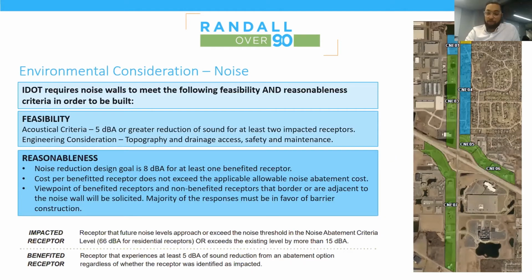Now, I'll briefly summarize what steps are yet to come from a noise perspective. In addition to existing measurements, a traffic noise model will be generated for both no build and build project scenarios with expected traffic counts in the year 2050. To be clear, the no build scenario is the scenario in which the project is not built and the existing alignment modeled with expected traffic volumes for the year 2050.